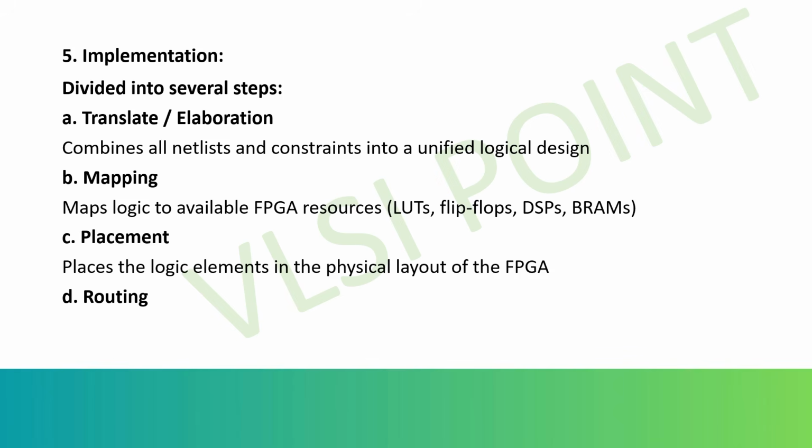Then there will be place and route. So place logic elements on physical FPGA locations, and then during routing it will connect them through programmable interconnects. Here the FPGA tool automatically finds the best placement and routing. You need not do it manually.